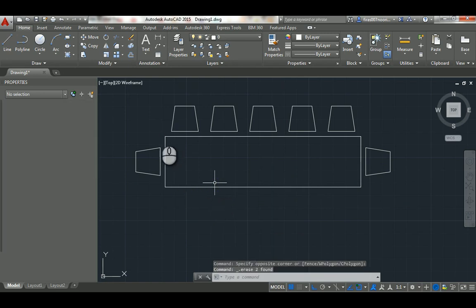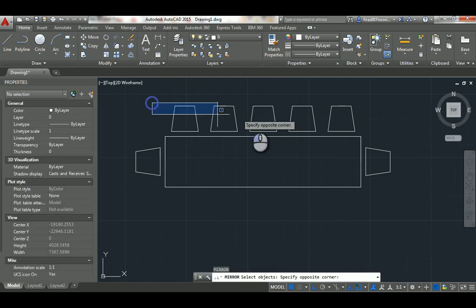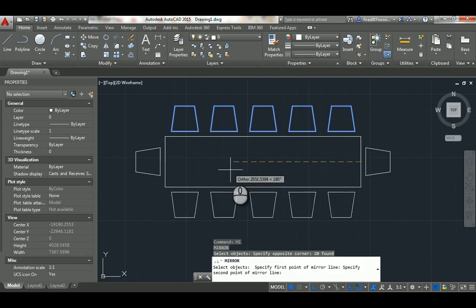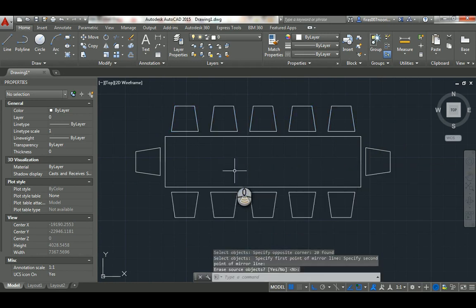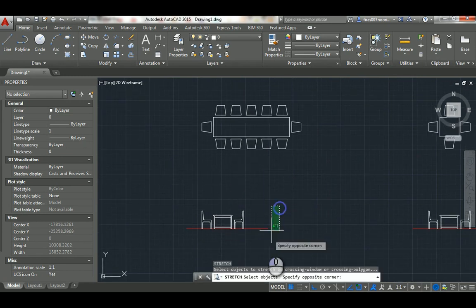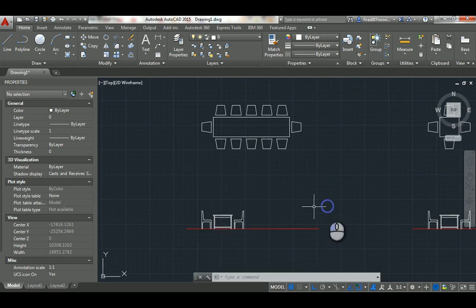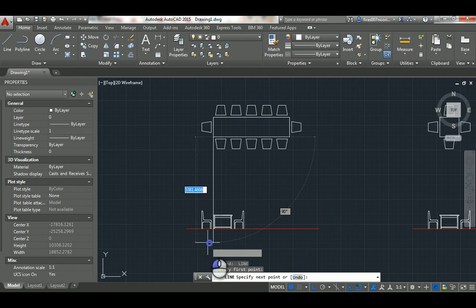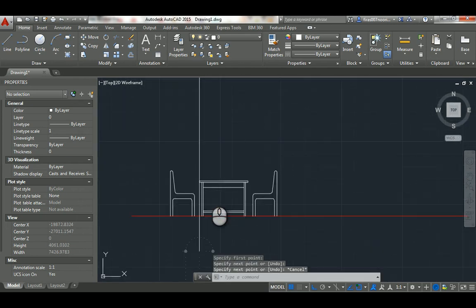And mirror is your friend always, if you know how to use it correctly. So from this midpoint to whatever to the right, and then hit space. And that's what we want for the plan, for the elevation. Again, don't draw, stretch. That's the trick you need to know. So push that down, just take the projection.